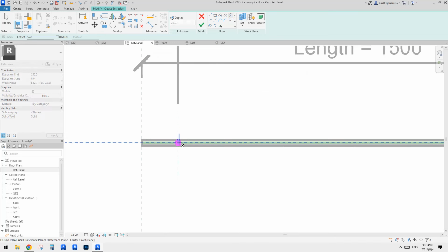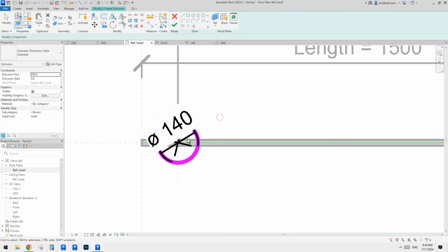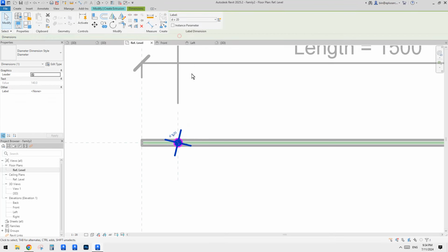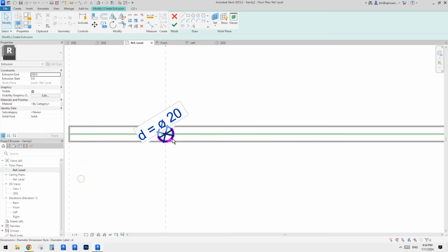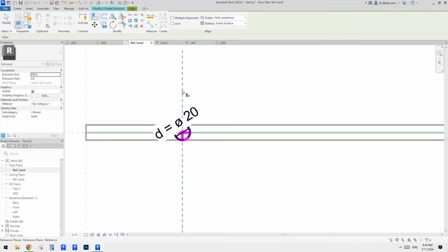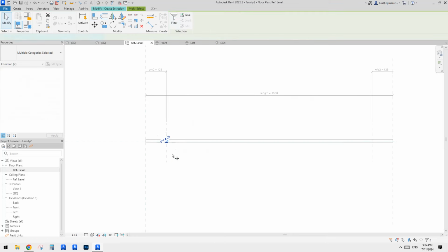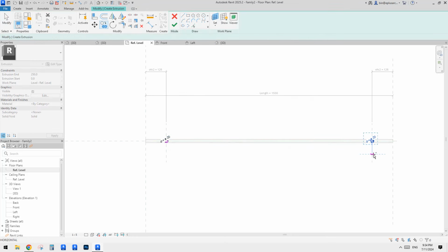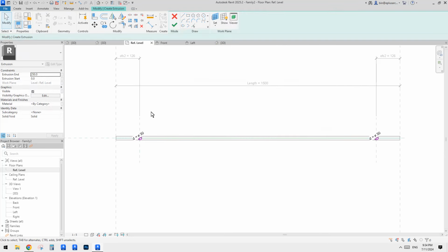Let's just draw it from here. Same diameter, select it, and then apply the same to it. Don't forget, maybe change the scale so we can see the lines. Select the line and check the center mark visible, AL, align, and the lock, and maybe this direction as well. Now we can select this one, reference plane to this, AL, lock. So now we have a vertical member as well.